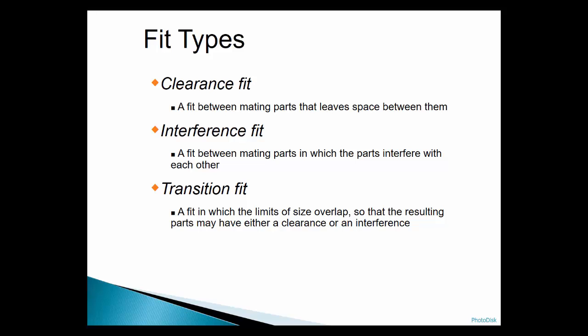How is this achieved, you ask? Hydraulic presses, thermal fitting, and big old hammers are used to make interference fits. The last fit is transition fits. Transition fits could have clearance or interference depending on the actual measurements of the parts.